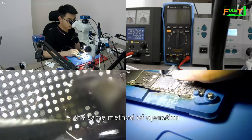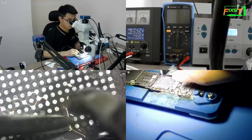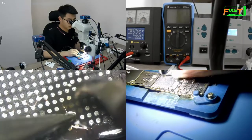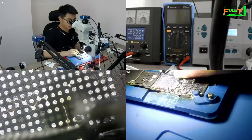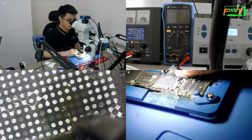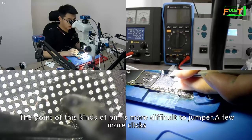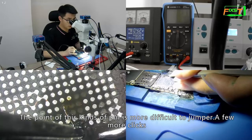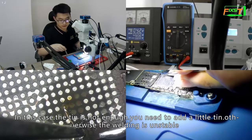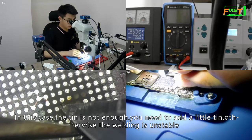The same method of operation. The point of this kind of pin is more difficult to jumper. A few more clicks. In this case, the tin is not enough. You need to add a little tin. Otherwise, the welding is unstable.